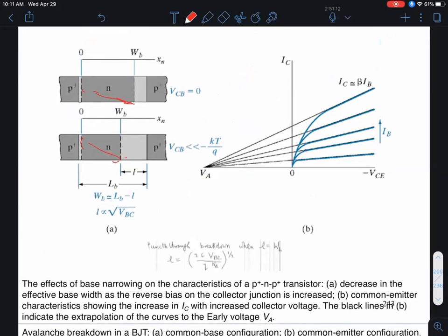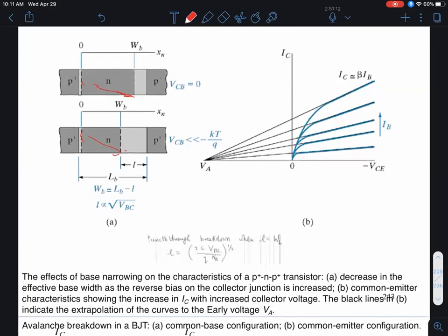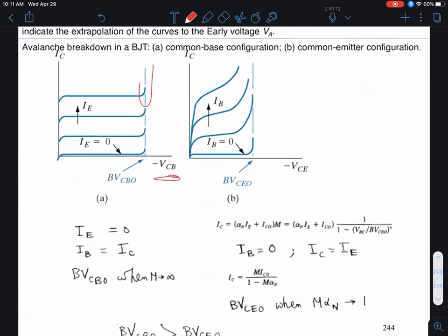How about tunneling breakdown? Is that a possibility? No, it's not a possibility in this context, because for tunneling breakdown, remember, you need a very narrow barrier, right? Which then requires a very high doping on both sides of the junction. You need a P plus, N plus junction. But typical collector dopings in a BJT are not high. They're low because you don't want the base collector to break down under reverse bias, okay? So the depletion regions are going to be too wide for tunneling breakdown. The breakdown is going to be due to impact ionization or avalanche breakdown, okay?